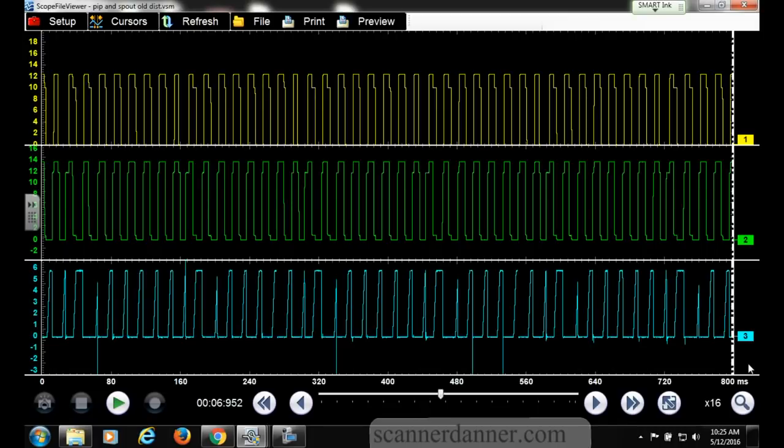But then again, we're also seeing it here and here, so that kind of changes it a little bit. I don't know that the spike shows us really anything more, but do you see what you don't want to see on any distributor engine? Where you got one coil that's firing over and over and over again for every cylinder, you should not see that kind of dwell time variation.